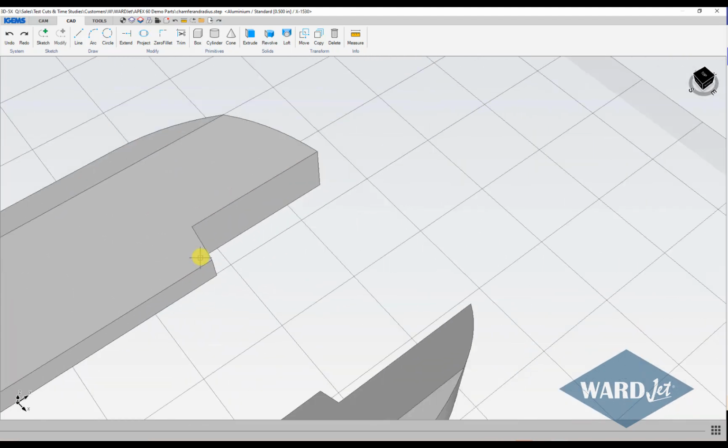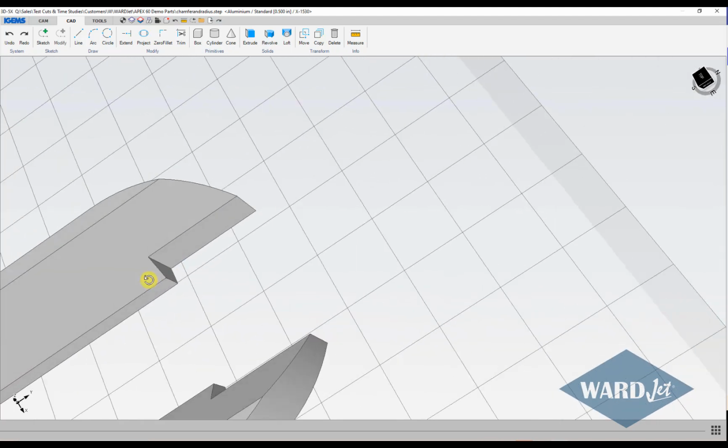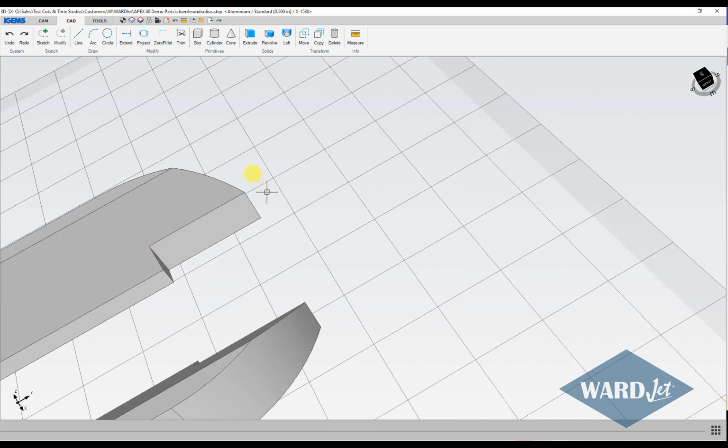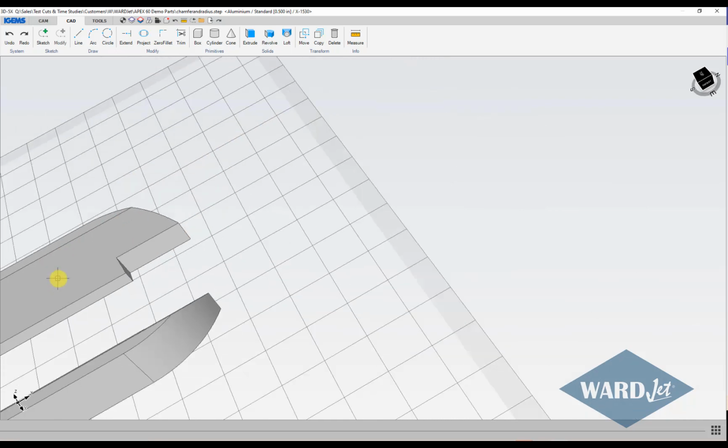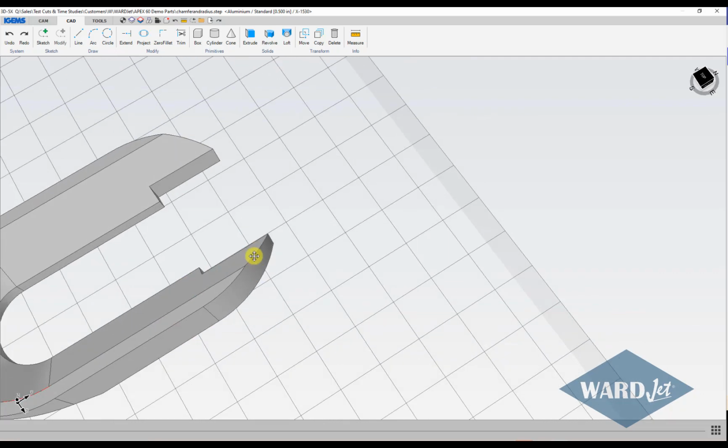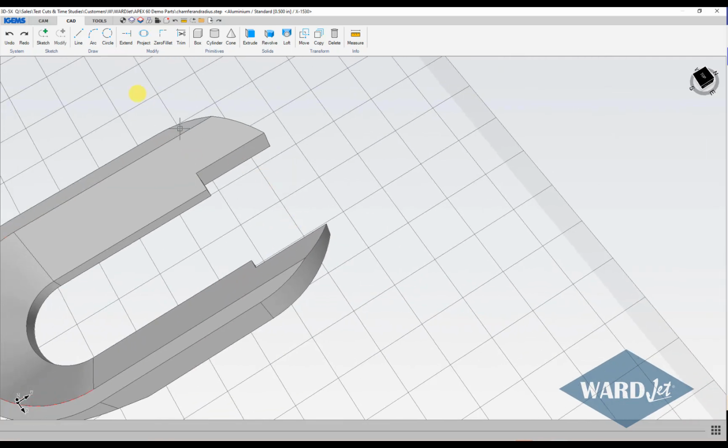So what I'll typically do on something like this, so that I've got a nice continuous fixed angle, is extend these edges and we're going to extend them out to the end of the model here, so we'll be able to come in nice fixed angle, and then same thing on the other side leading out. So handy command for that on the CAD tab is this extend.